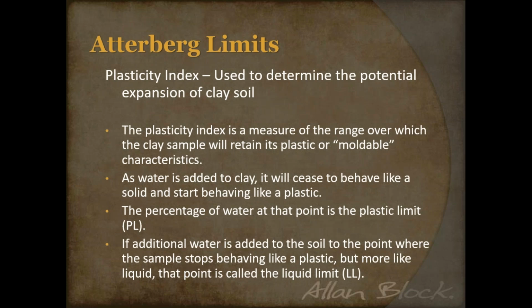And so we really need to identify the plasticity index, and that just measures the range of how plastic or how moldable that soil is, because it's really temperamental when it comes to water. It has to do with fat or lean clays. And I should point out that these Atterberg limits, I've got a handout also attached as well.